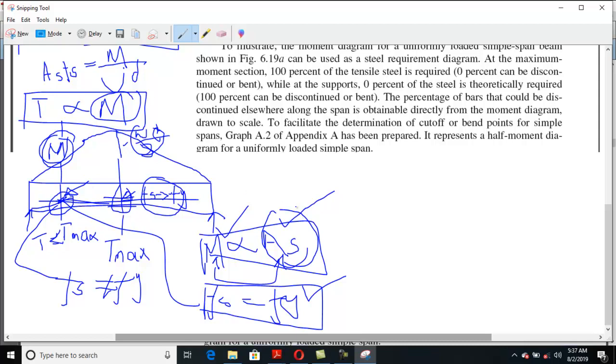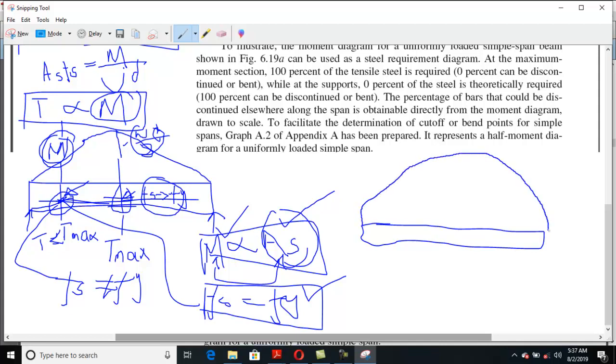One important criteria is also there that, for example, along the length of the beam, at the point where there is the maximum amount of moment, you need the full development length of the bars, because you are assuming that Fy stress will be produced.